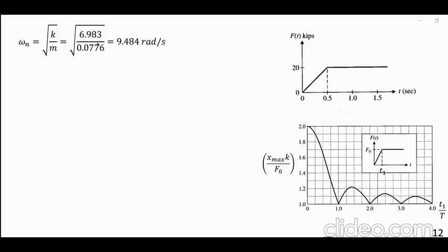Okay, so now we go and calculate the natural frequency, square root of k over m. You just found m, you just found k. Remember, we're adding those three stiffnesses. You get this. And you find a period, 2 pi over 1.51. So in this expression, the T that you see is this number. Now, for the loading that we have, little t1, because in here, you have little t1, is 0.5. 0.5 over that is 0.331.